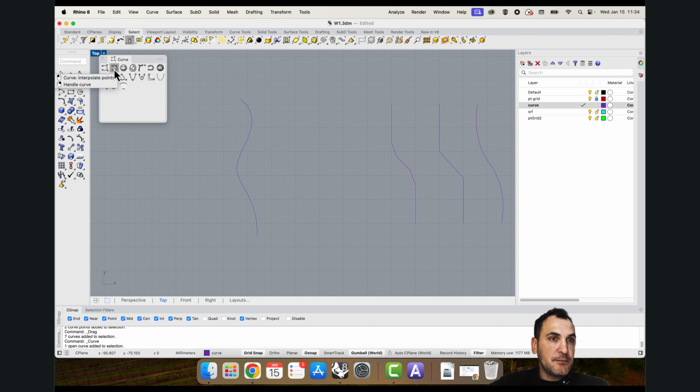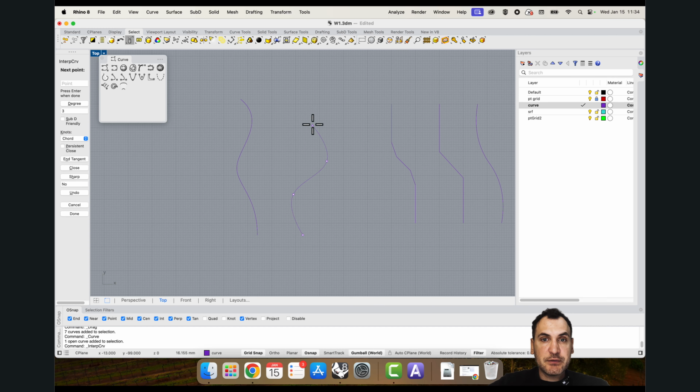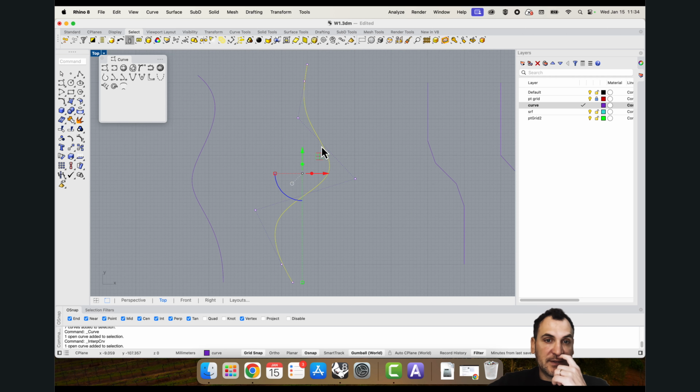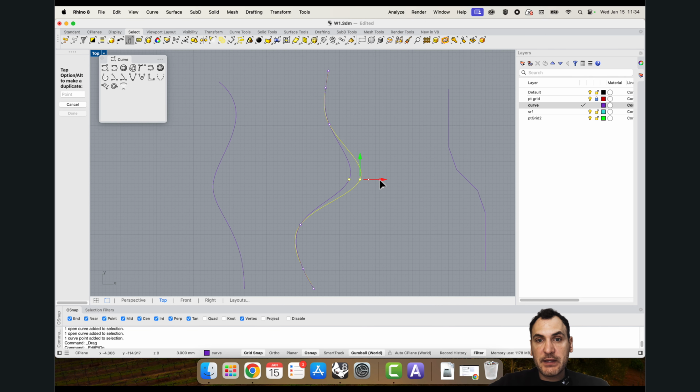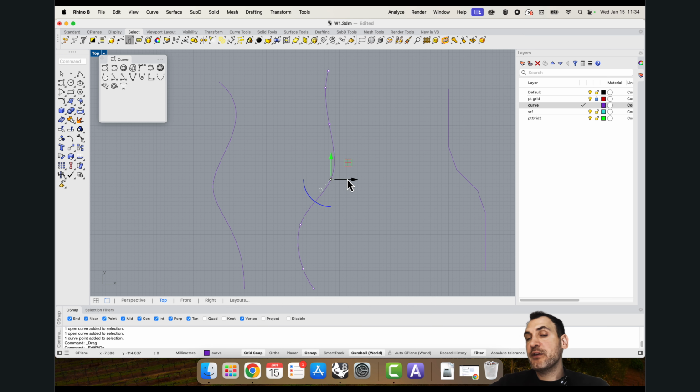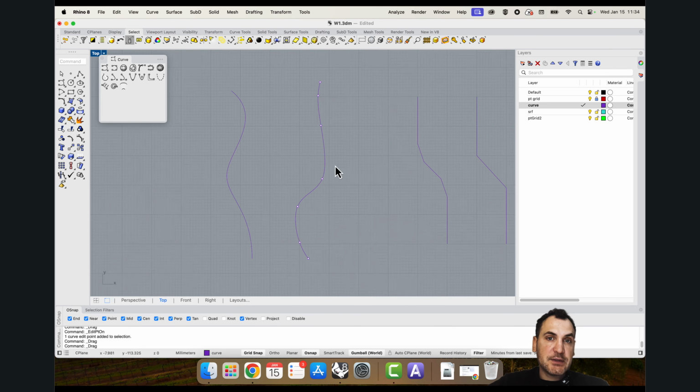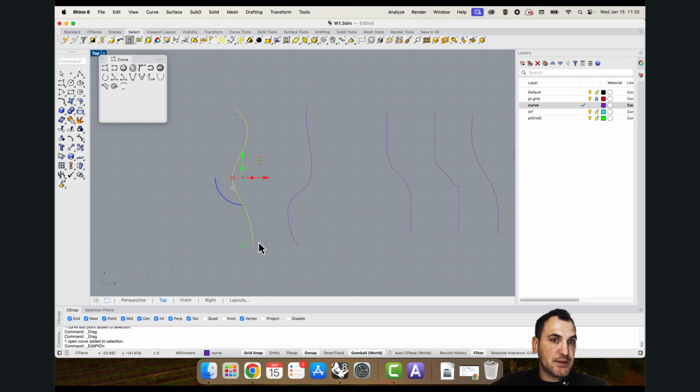But if you do interpolate points, this would actually register points directly on the curve itself. But then you can also see these control vertices, and we can modify either one of them. So you can control the curvature through these vertices as well. Or if you go here and turn the points on and choose the curve, you will be able to directly control the topology by moving a point on the curve itself. Right, so there are two different ways of plotting curves, but they can essentially interchange. So I can also find these points on this curve as well and manipulate them here too.